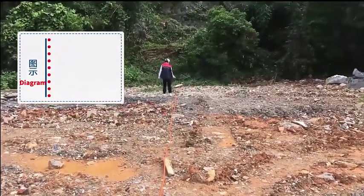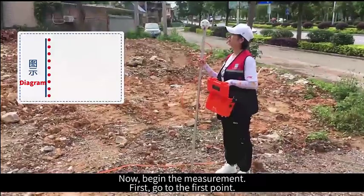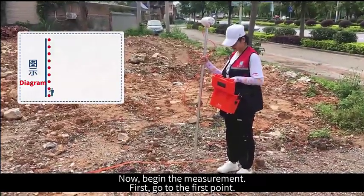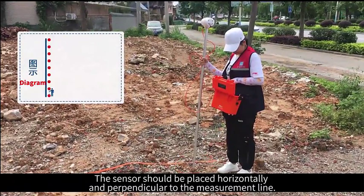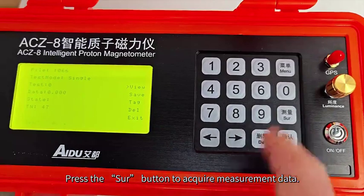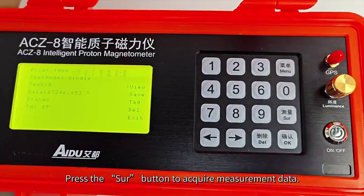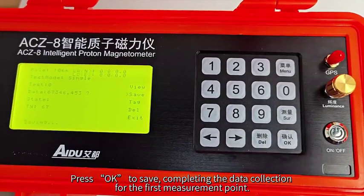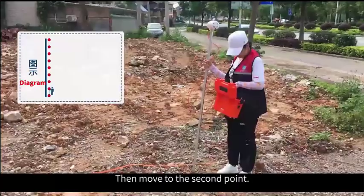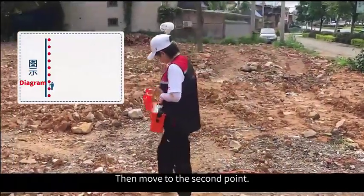Now, begin the measurement. First, go to the first point. The sensor pole should touch the ground. The sensor should be placed horizontally and perpendicular to the measurement line. Press the SIR button to acquire measurement data. Move the cursor on the screen to save. Press OK to save, completing the data collection for the first measurement point, then move to the second point.